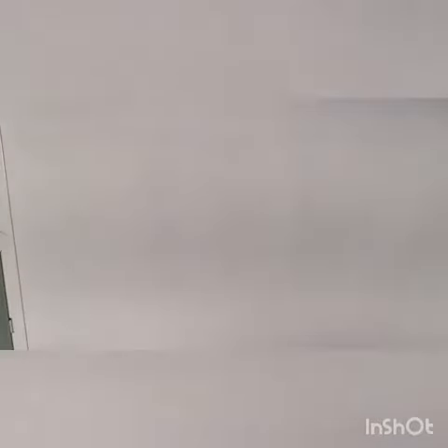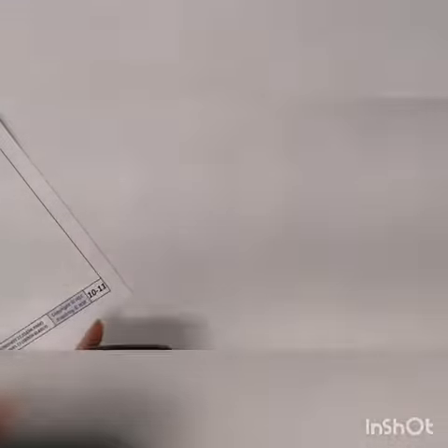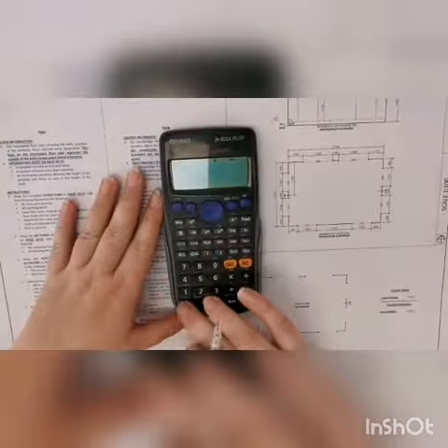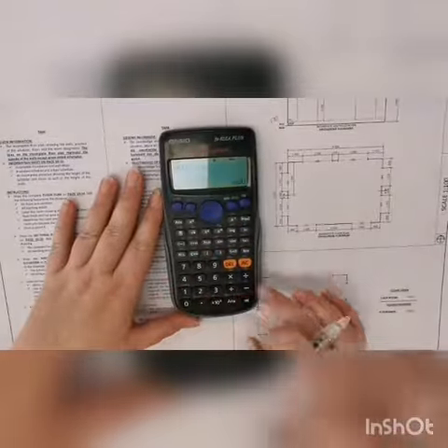And I must also just note that the floor plan we are drawing is scale 1:50. No, 1:25. That means any real life measurements I'm given on my floor plan, I divide by 25. So let's get the outline going. 8,000 divided by 25.